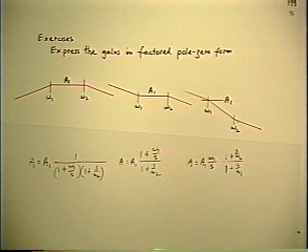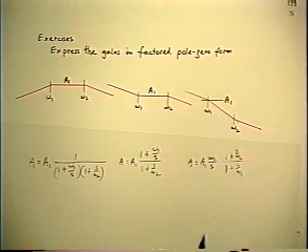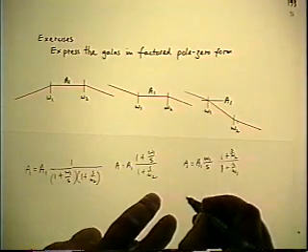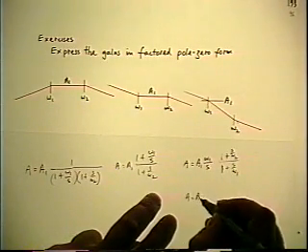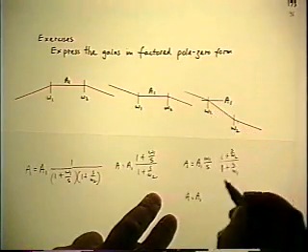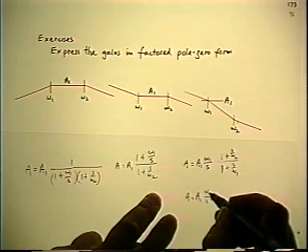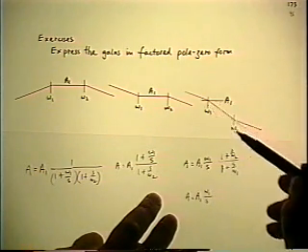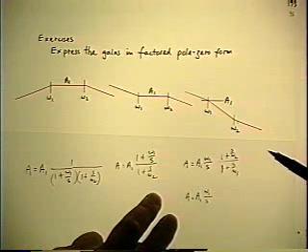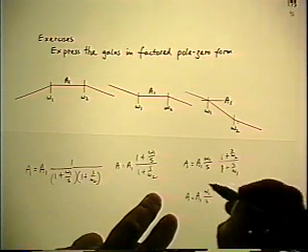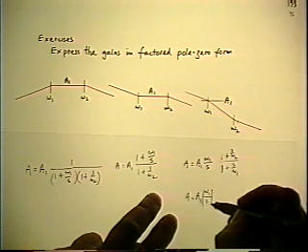So that's one version of the result. But as I said, you have a choice. We could have identified the A1 originally on the middle slope, in which case the first thing you write is A equals A1 at the frequency omega 1, so S will be in the denominator and omega 1 will be in the numerator, but this time if we identify it with the middle slope, it's a double slope, minus 40 dB per decade, which means you have to square that term.